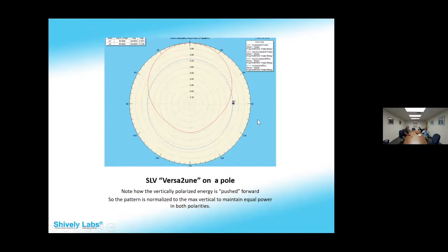But we are in the process of sweeping and measuring an antenna and proving the HFSS twin of it. Through that process, we verify the range and verify HFSS and position ourselves for that eventuality of having computed patterns accepted. And there are some advantages to doing that.